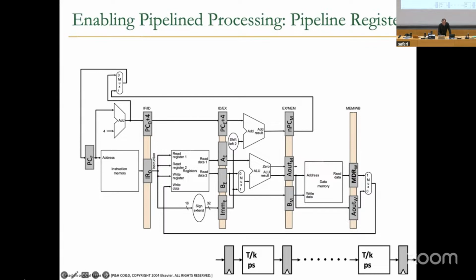Okay, so hopefully it's clear. So now we went through almost the entire pipeline, and this is how you construct the data path. And you need to ensure that no resource is used by more than one stage. So here, for example, when we're writing the data over here, this write port is not used by anyone else. Only this instruction, the write back stage.